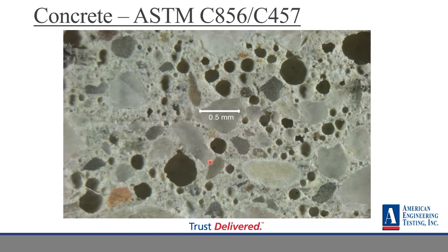On the flip side of that, interior concrete slabs, like for flooring, typically specify that air entrainment must be below 3%, and that has to do with different finishing techniques. So if they have some issues with the finish of the floor, and we do an air analysis and it's above that 3% limit, they'll probably go back to the ready-mix producer, the concrete producer, and talk about who's going to pay to fix the issue.